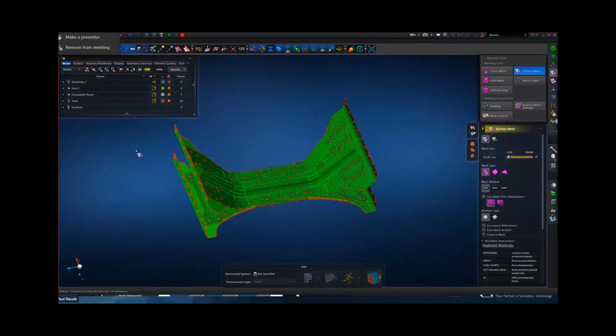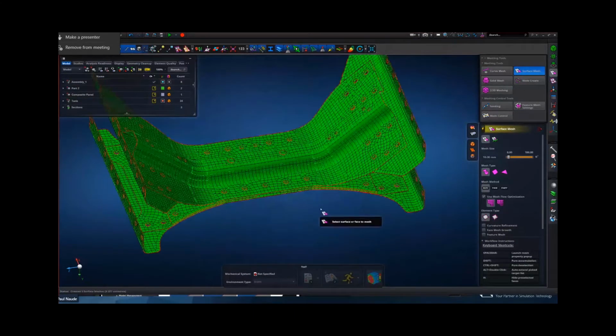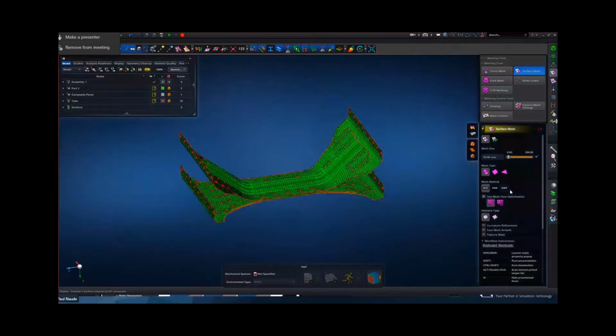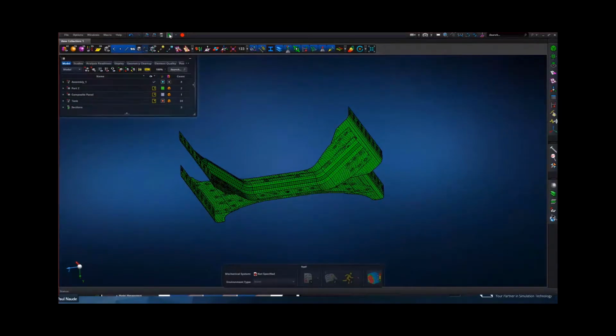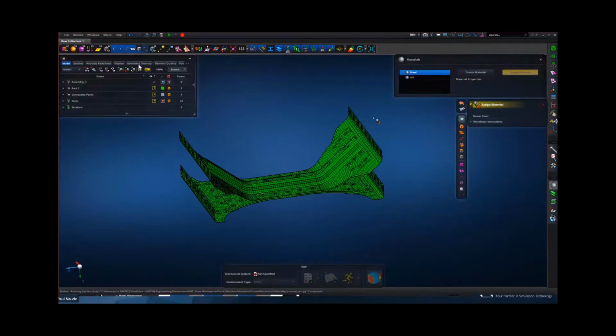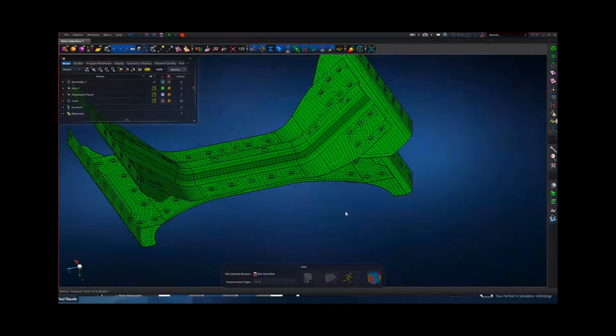Sorry, I see I missed a few on that side. So let's just mesh that again. So there we have surfaces that now represent the original solids, and we can assign a material or quickly create your library of materials using a little script if you like. And I'll just assign my steel to these guys. Now these plates are not connected yet.